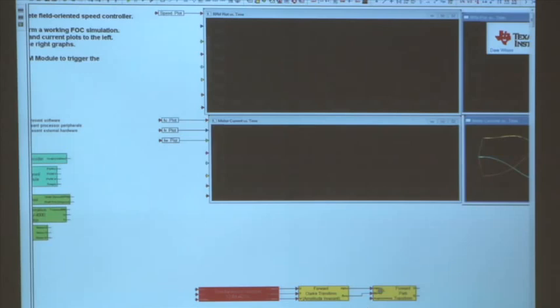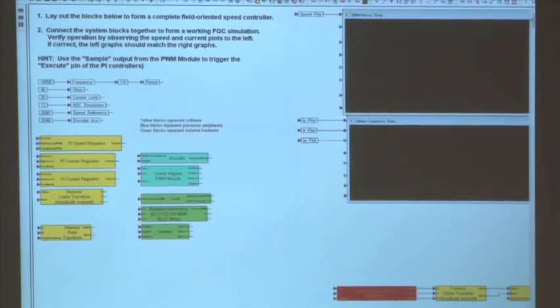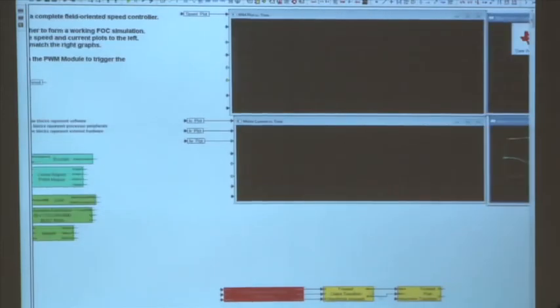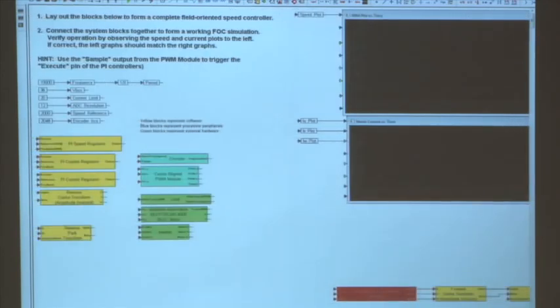Okay. So now that I've transformed my currents into D and Q, what's the next thing I do with those currents? They're now up on the rotating reference frame. Now I generate the error signals, right? I'm going to put them into my regulators. So let's go find some current regulators. I've got 2 of them here.